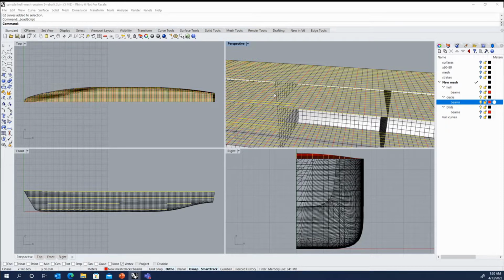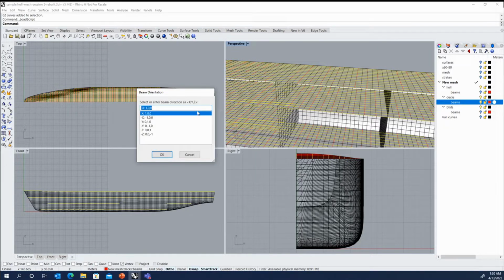So if you have them selected ahead of time and then run the script, and I say polyline and direction. Now, if you're running polyline and direction, it doesn't care if that beam trace is on the mesh or if it's just out in 3D space somewhere. It's just taking a polyline in 3D space and you're specifying the direction, and it'll just write that out into a Maestro neutral file. And when you pull it into Maestro, you'll have a beam sitting out in space.